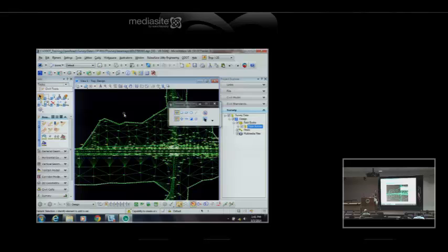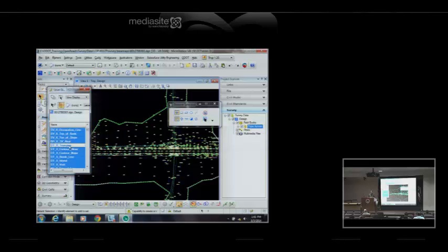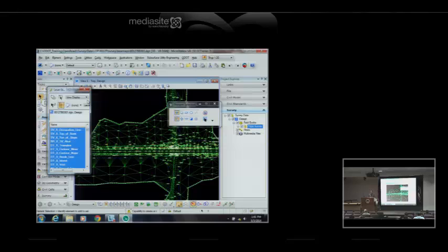All right. Now, these are still graphics just drawn on a level. So I could still come to MicroStation levels and come down here and find that DT triangles level, wherever that's at, and turn them off that way if I want to do it that way. So it's still MicroStation graphics, just how they're controlled is a little different by feature.